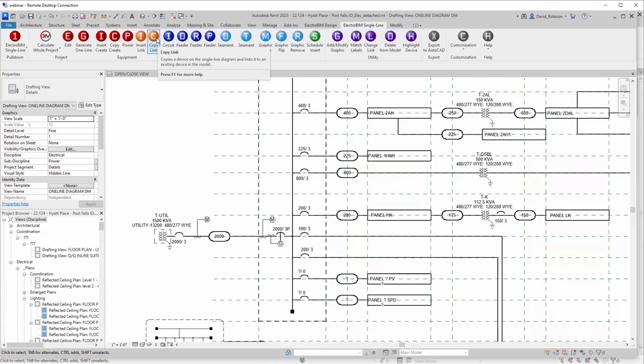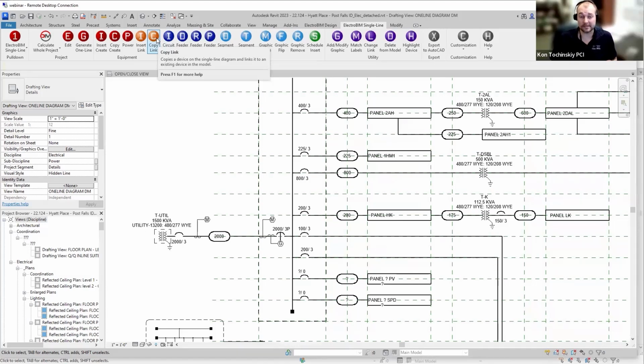Question for you on that template that you are describing. Yes. So you have a template Revit project, and you have in the model the transformer and the switchboard inserted just kind of off in space connected to the single line. Is that correct? Actually, we typically don't have the switchboard or anything connected. The template is actually not connected to anything. It used to be connected, but because when I got rid of all the devices, it's actually not connected to anything. So when I come back, I change the link and I find the switchboard that I plug in.